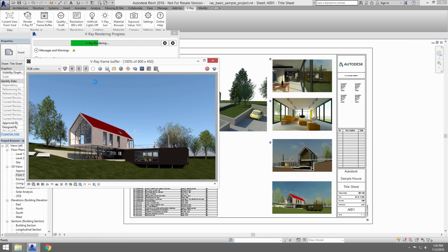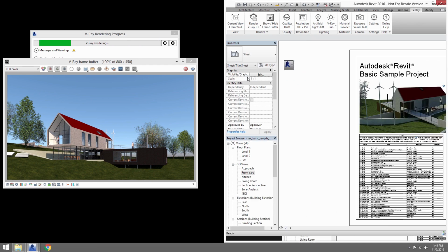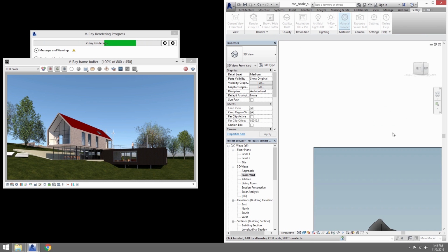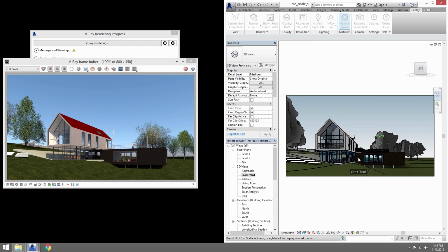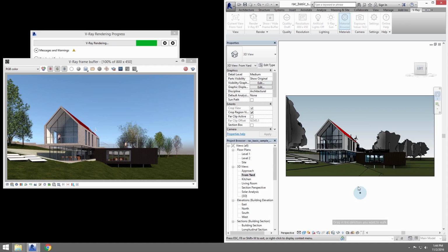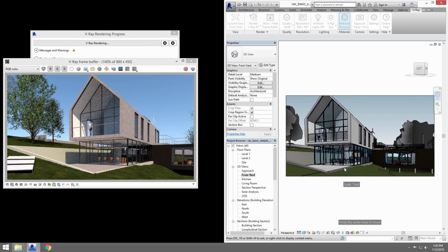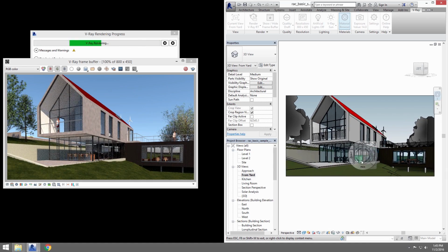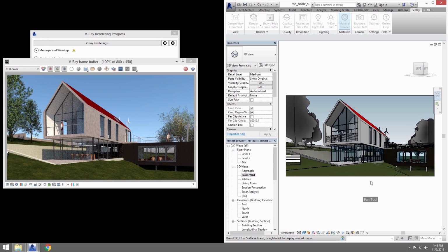Let's change the location of our view by moving the camera around. With the window to the side, I can see the rendering while still able to work my settings. Let's go back to the From Yard view. Go ahead and press ZE to zoom extents to make this easier. And then open up the navigation wheel and orbit the view. As I do, you can see how RT updates the render pretty quickly. Go ahead and settle on a view you like. I'm going to settle here in my view, checking RT to see the render result as I go.